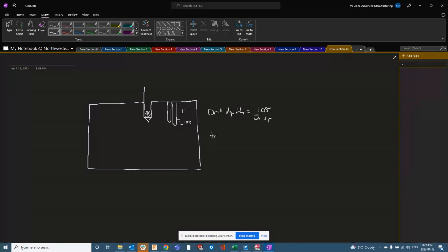right? And then our tap depth, if we're just doing an inch, we could just say equals -1 in this case, and that should be negative up there too. And that means that the tap is going to come down to here, which gives that extra 50 thou that we drilled, just a little bit of space. Normally companies are okay with you drilling a little bit deeper in order to get 1 inch full of tap. And then when you're tapping, also make sure that your tip comp is on as well.